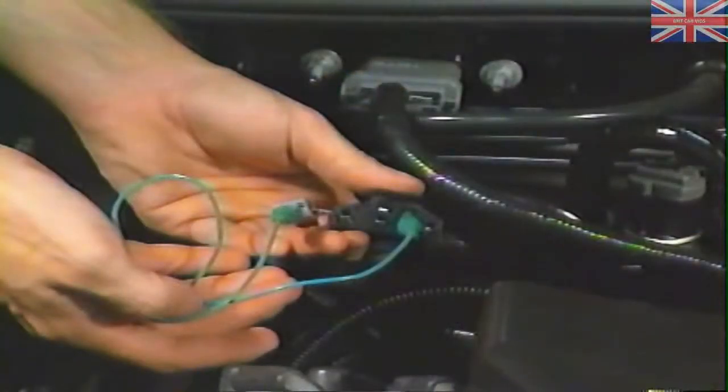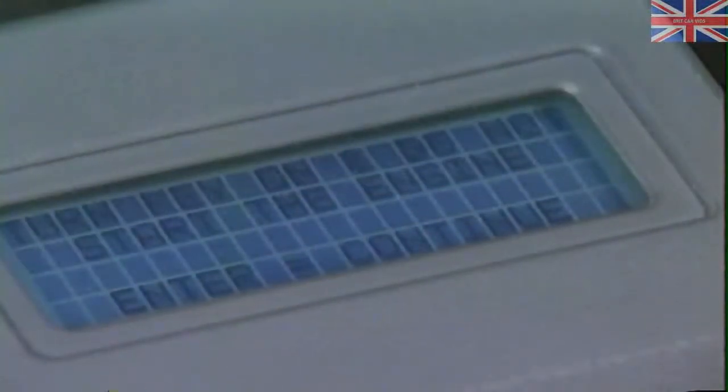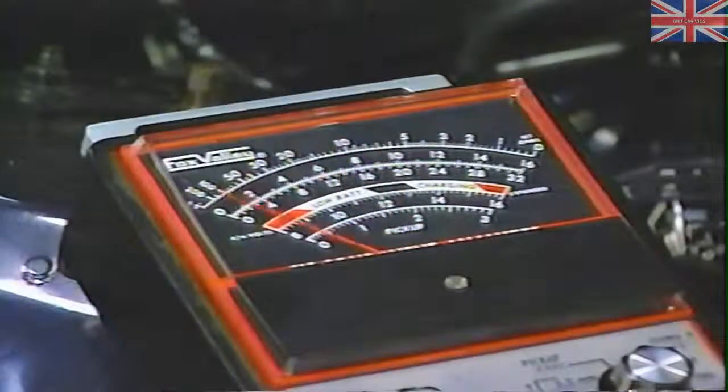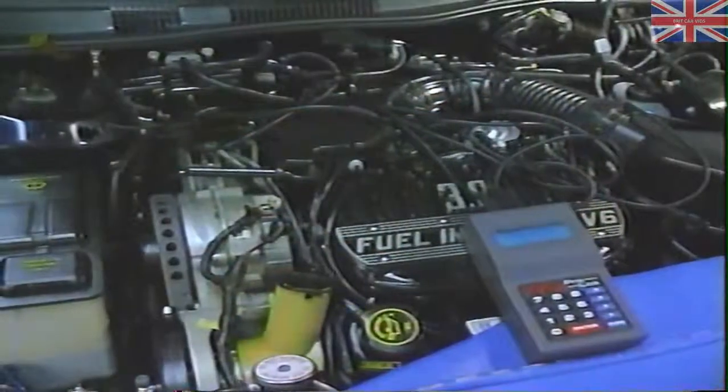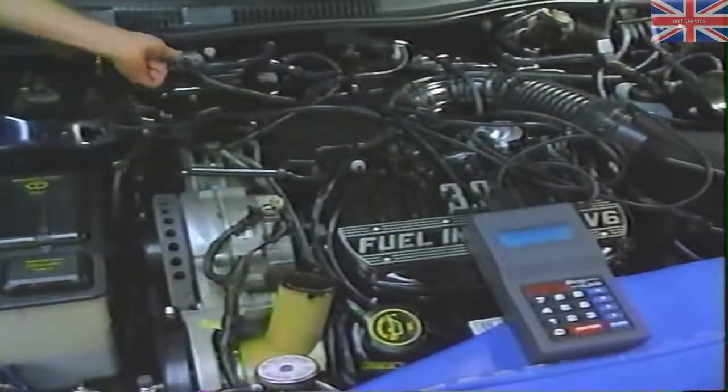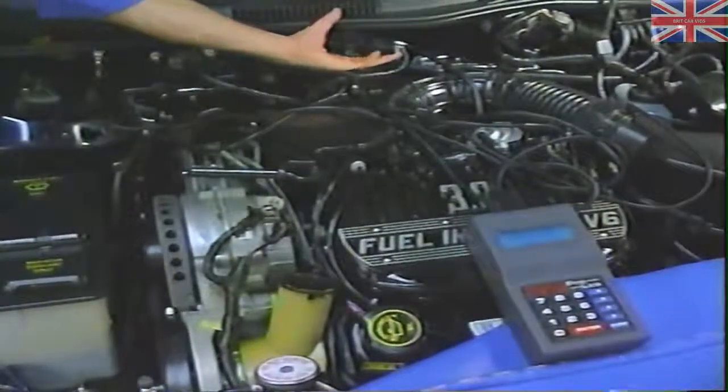Re-enter self-test and disconnect the jumper wire from the self-test connector to erase any diagnostic codes. Turn the ignition key off. Wait approximately 10 seconds and reinitiate self-test. Key on, engine off. A passcode 11. A separator pulse, then another passcode 11. Now, start the engine and repeat the wiggle test and watch for a diagnostic code.